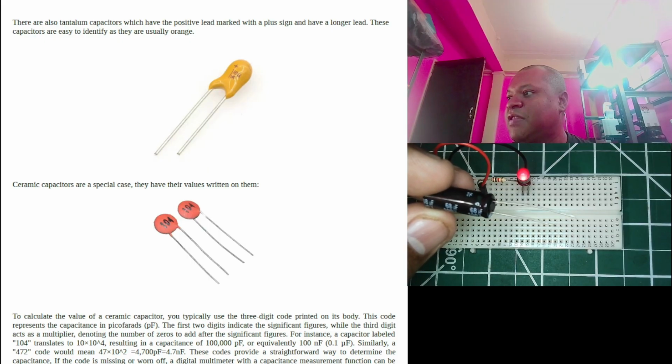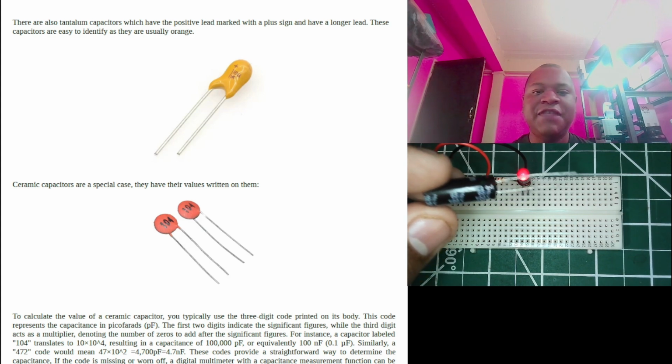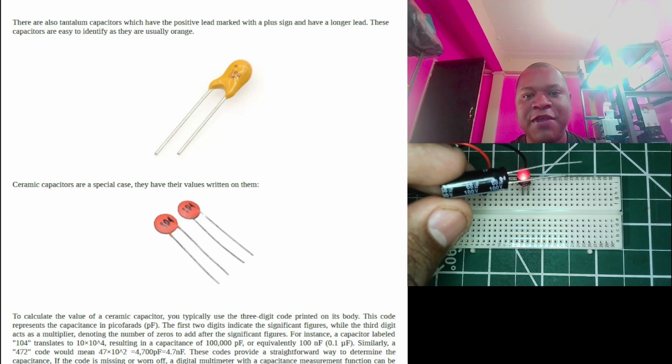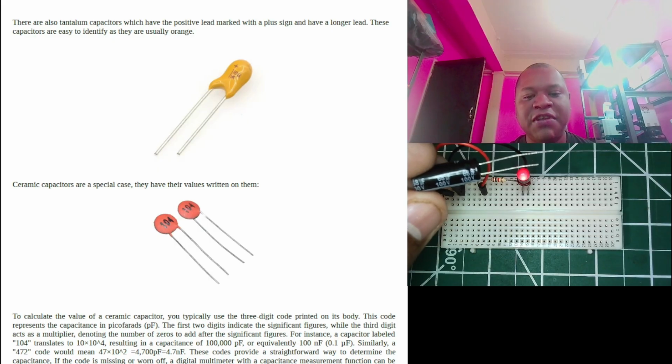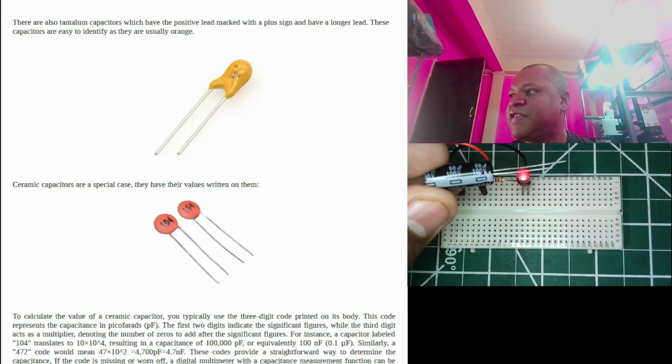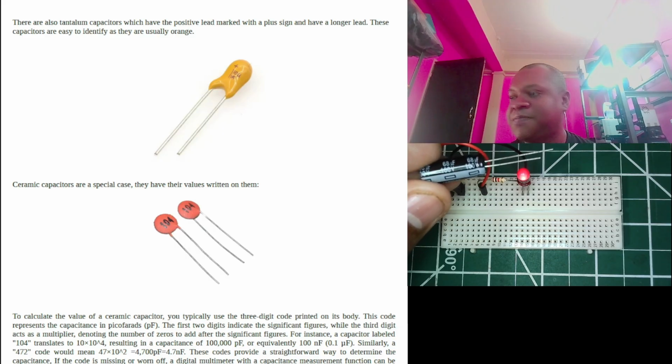I also want to talk about the capacity. You see marked on it, you have 68 uF. This F actually stands for farads, and farad is a really big quantity, and it measures how much energy the capacitor can store, the capacitance value. And it's a 68, and it also has a voltage on it. This voltage is the maximum voltage the capacitor can work in. We call it the working voltage. Sometimes you see WV, for working voltage, written on it.